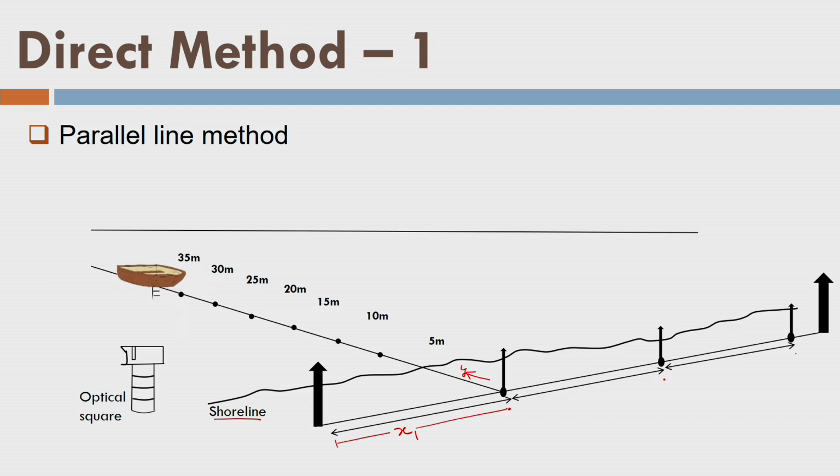Well, once this line is finished, the boat will be turned onto the next line like this. We will come back and observe these points also. That means we are observing the sounding at every point. Now we will repeat this process for the rest of the survey lines or range lines. That is the process in the parallel line method. We have divided the whole area of interest, or the river body, into parallel lines, and we are observing the sounding readings as well as the xy position at regular intervals. So, I am getting a very nice grid of data x, y, z.